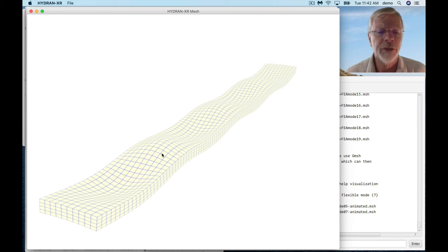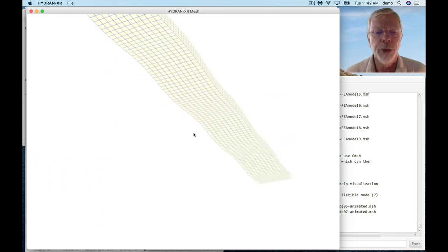But these are the kinds of deformational modes that the stiffeners are probably going to prevent from happening, these boils, so to speak. This mode shape and the natural frequency associated with it is so high that it's unlikely to contribute much of anything to the structural response. So we're not too worried about it.